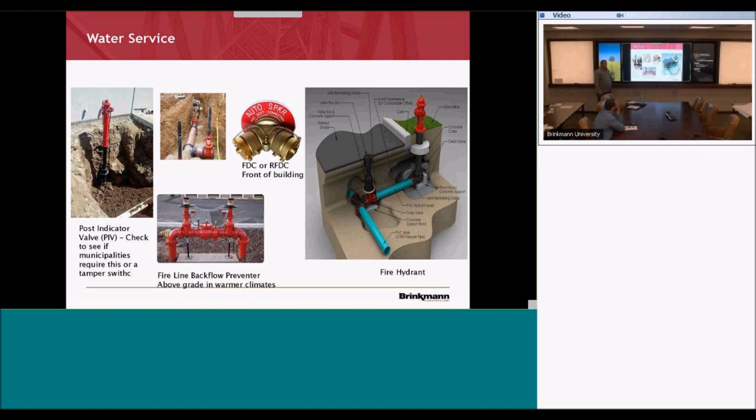Yeah, there will be, or there should be, some specifications that come from whoever the water authority is in that area. Similar to how MSC has their specs, Missouri American Water would have their construction specs that say, per AWWA, you need this many thrust blocks or you must use the Mega Lug here or there. So typically those come back with whatever information we get from the water company in that area.